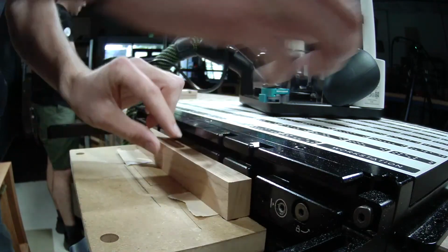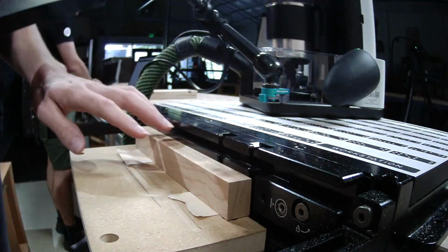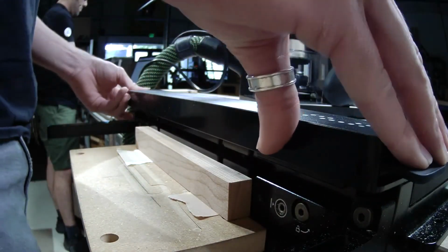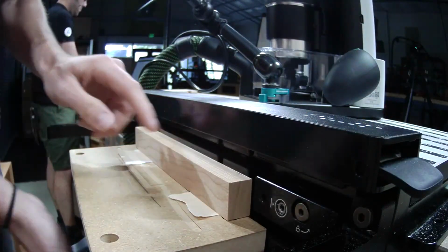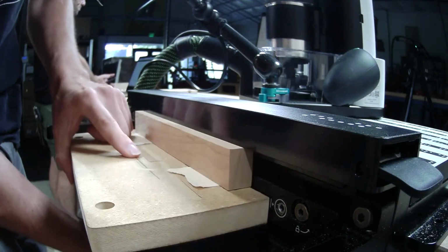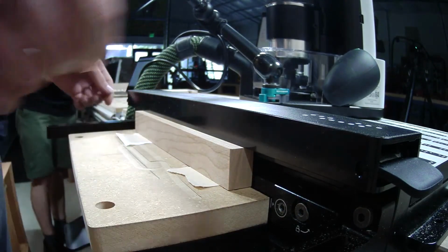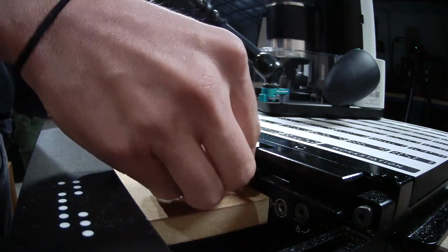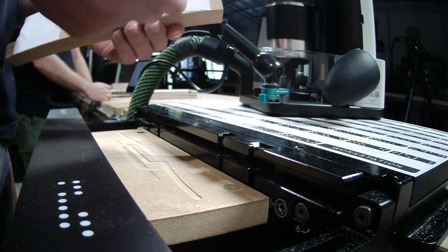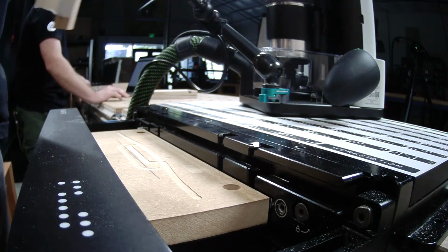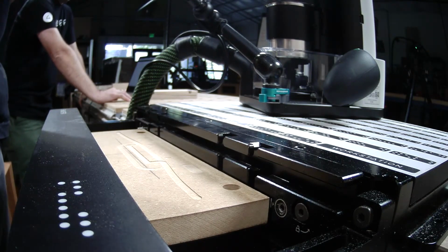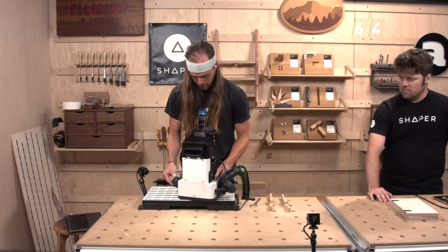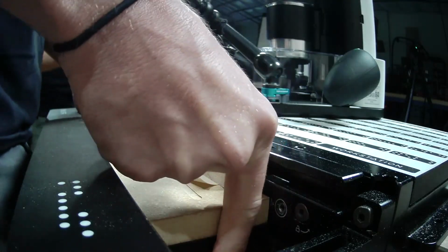So quickly, I like to use this method, which is put the tape down on the piece, just one-sided, take the support bar and put that on top. This allows me to quickly zero out this piece and raise it up until that makes a perfect mate. So now I can take this off, put this back onto my piece here, and now I know this is perfectly aligned. It's going to be a little bit lower because I didn't take the tape off, but in this case it's not enough to matter. So I will peel off the double-sided tape and put this against the back here. Give it a good pressure.